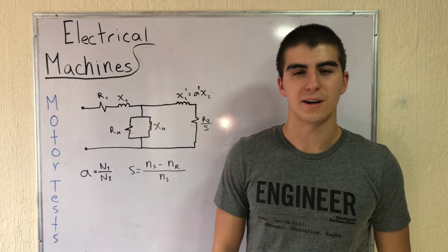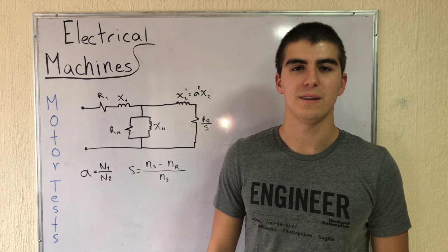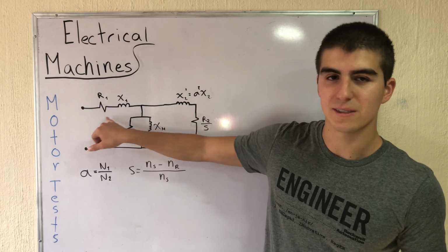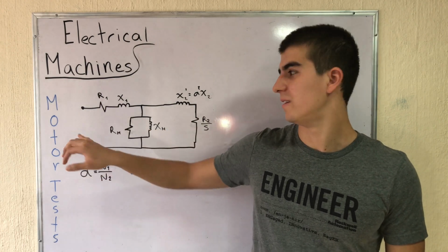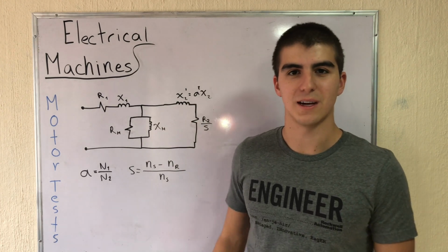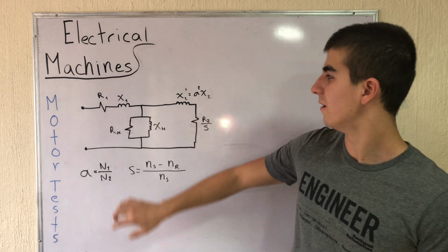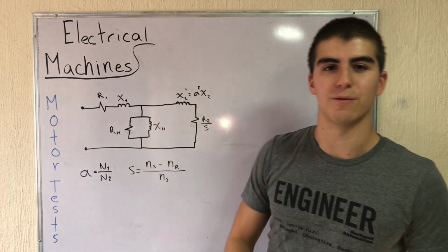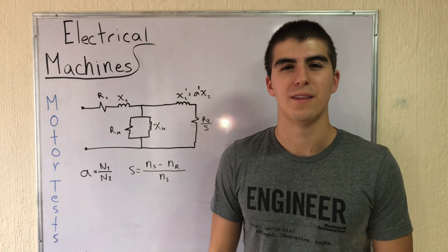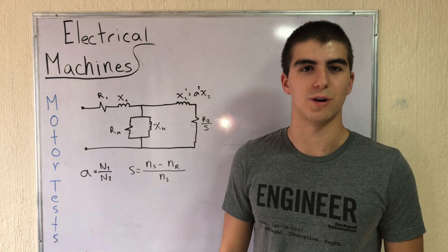To know the inner characteristics of an induction motor, there are two tests that need to be made in order to know the resistance and inductance values at the stator and the resistance and inductance values at the rotor. It is important to mention that this representation is only of one of the three windings that can be found inside of an induction motor.